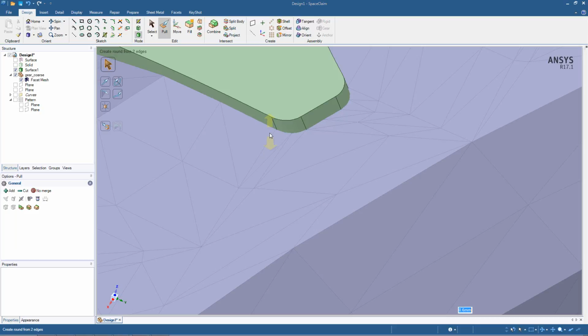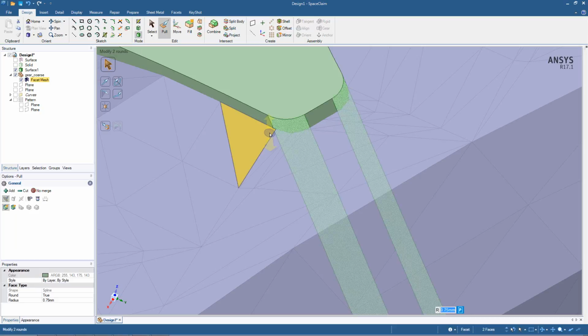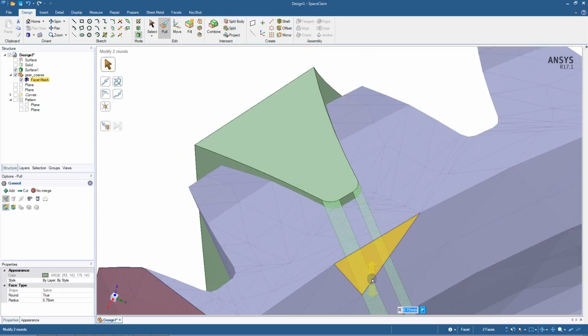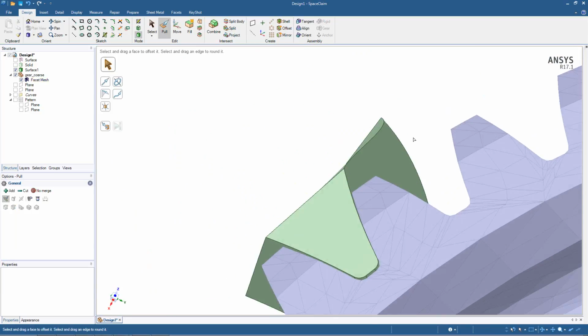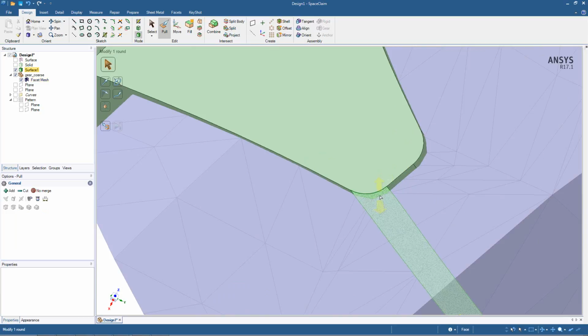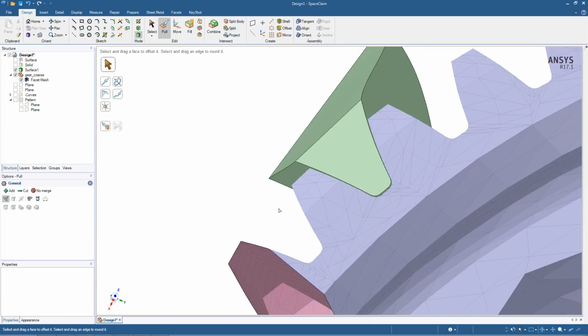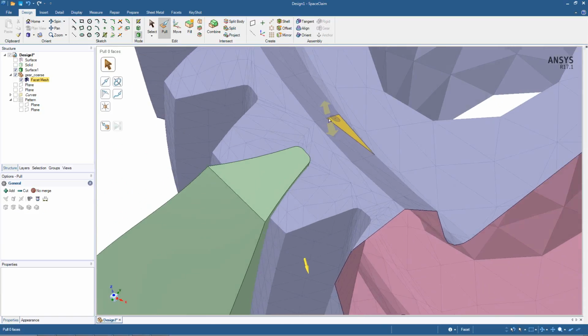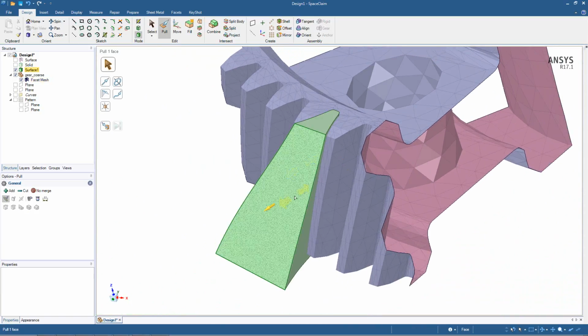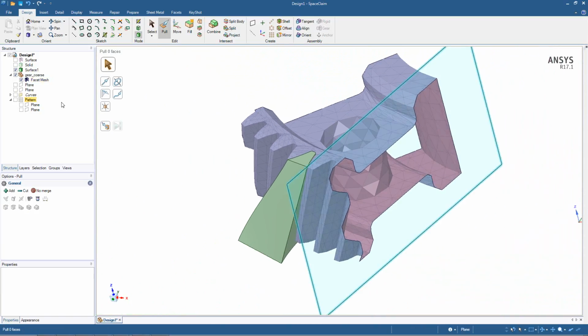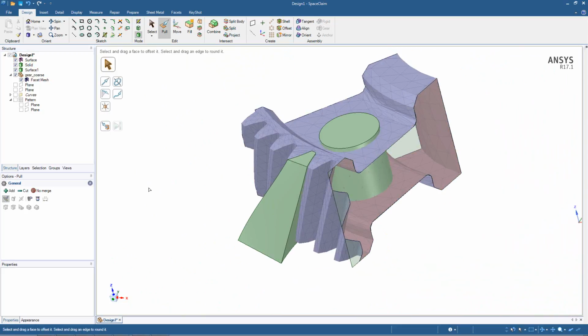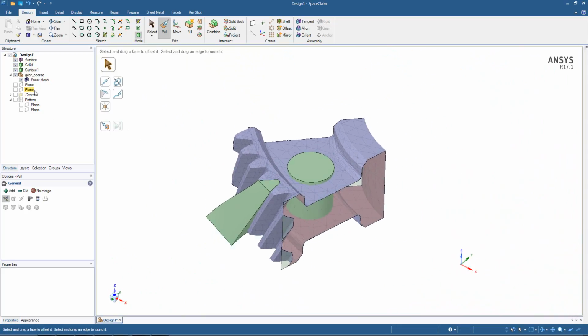And we can use the space bar and then free up the ability to type in a number, and maybe we just set that to 0.75. So set it to a number that we know would be manufacturable, or you'd have a tool bit that would make that. So now we have all of the geometry components that we need to rebuild this gear.